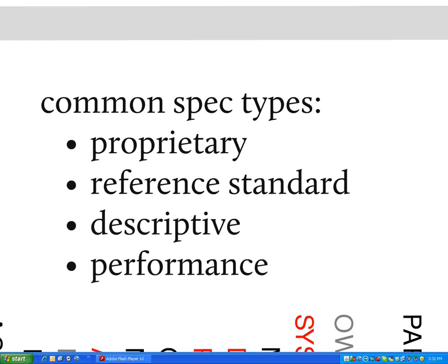And then performance requirements, because some of the performance requirements beyond air infiltration rates, for example, on a curtain wall, have to do with what is the acceptable deflection on this building that I've designed. What is the building movement? Is this a glazing system for a three-story building that's not going to move that much, or is it for a high-rise building that may sway several inches or even a foot or more at the top?